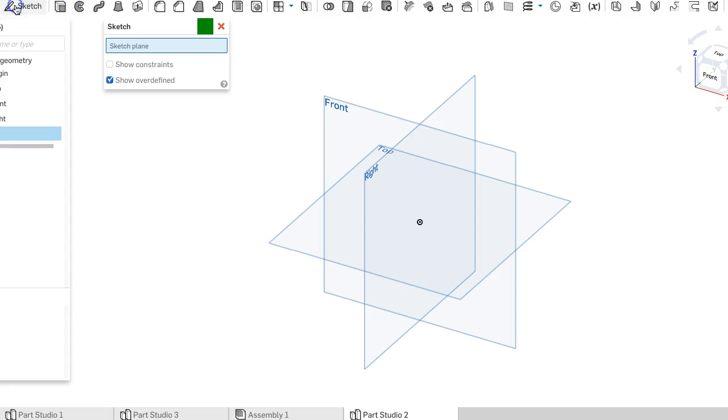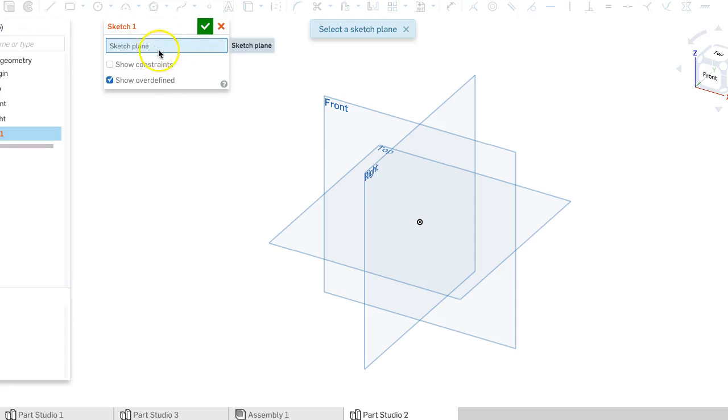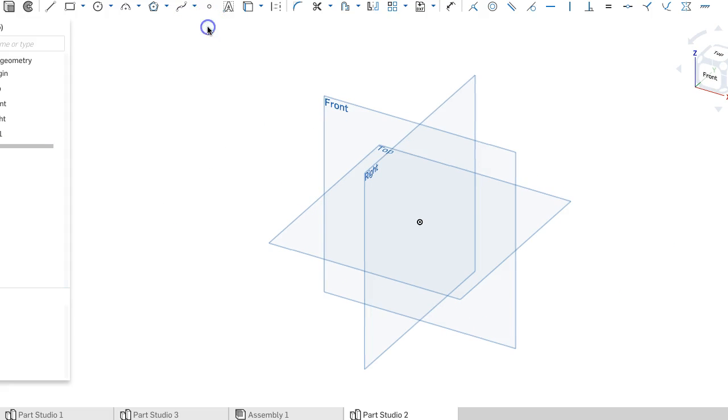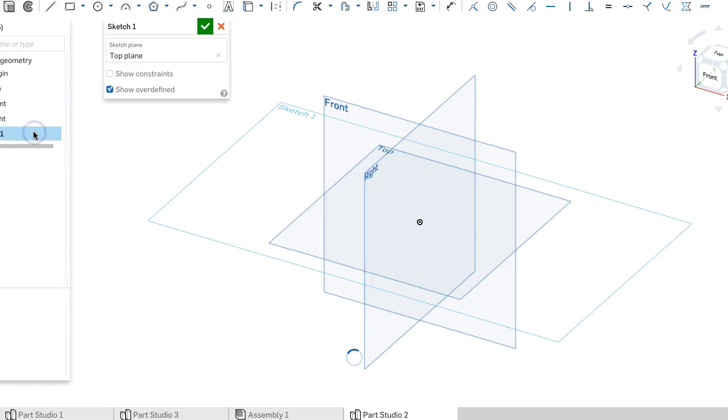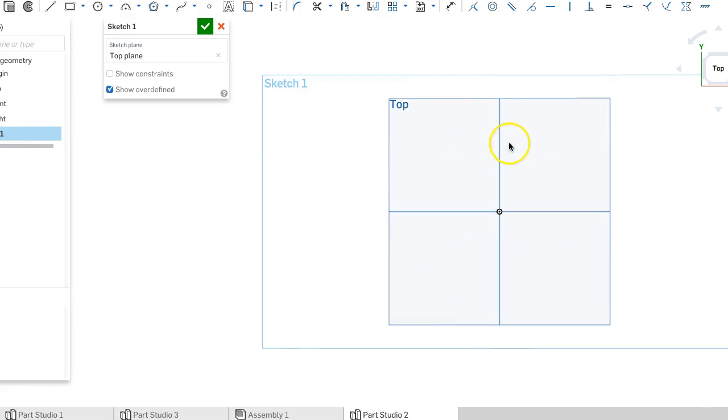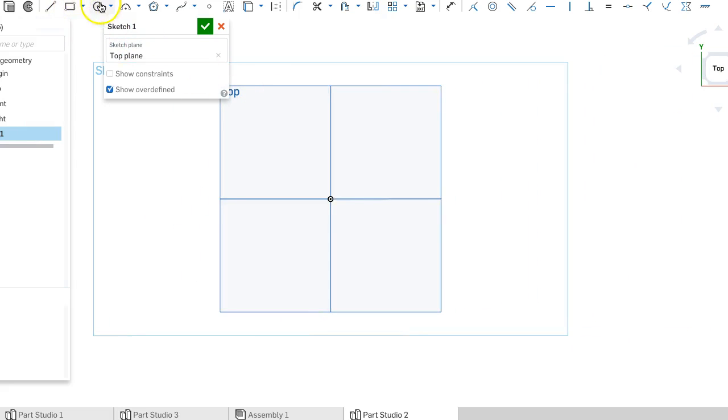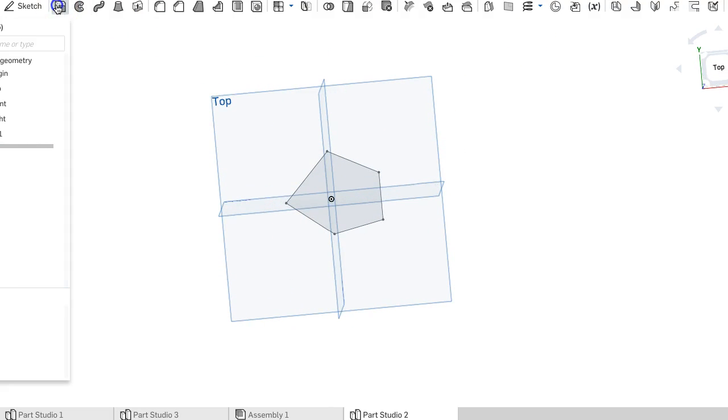To do a draft, we're going to start by creating a shape with an extrude. There's 2 ways to draft. I'm going to show you both ways. So we'll start by making a sketch. Oops. So double click on this to edit it. Press N to go perpendicular. And for this one, we'll just do maybe kind of a fancy shape. For this, I'm not going to worry about constraints, okay? And for your next challenge with the coffee mug, I'm not going to worry about constraints on the sketches. Okay, so we have this kind of shape here. I'm going to extrude it.